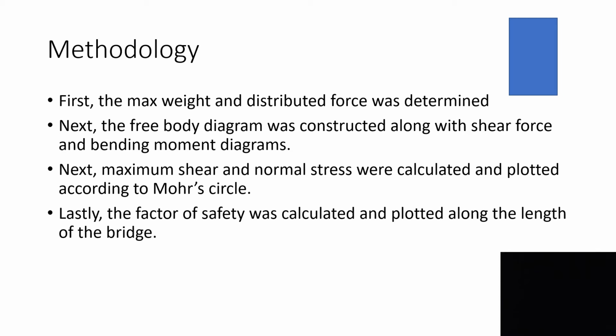Our methodology was to first find the max weight and distributive force. Next, the free body diagram was constructed along with shear force and bending moment diagrams. Next, maximum shear and normal stress were calculated and plotted according to Mohr's circle. Lastly, the factor of safety was calculated and plotted along the length of the bridge.